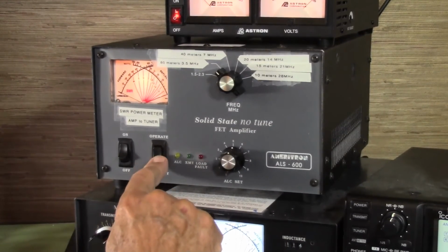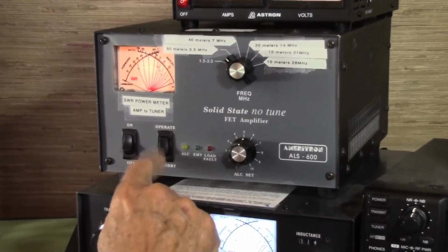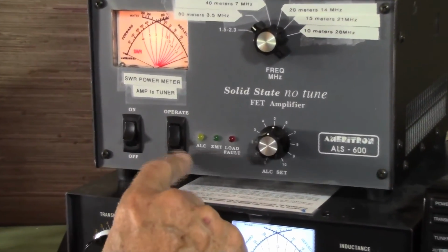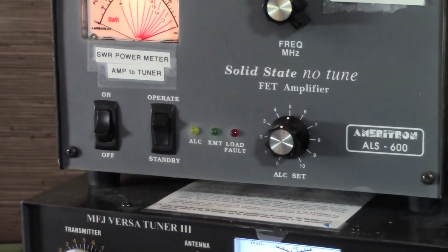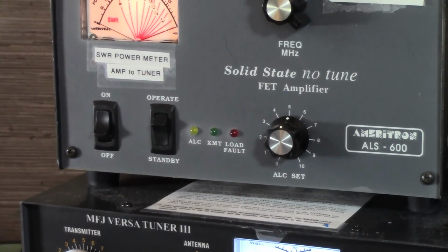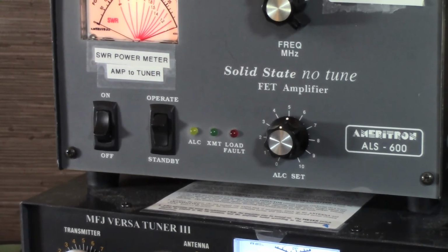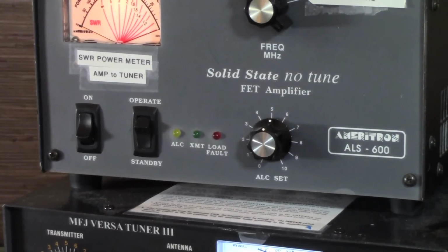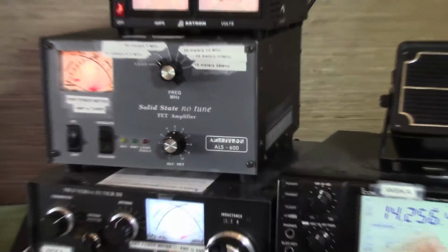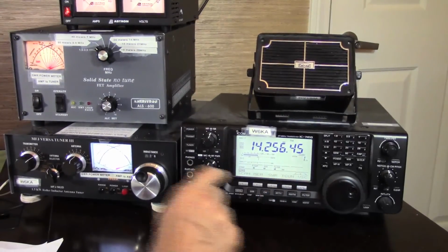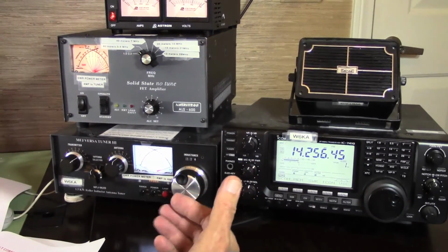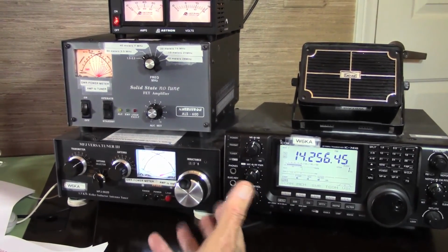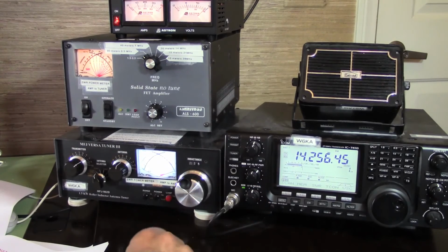I did show you that by switching this you can go back, but don't switch back right away. Let it sit and then check a few things. Here are the things you need to check. Be sure that your SWR is okay by, with this off, trying to retune it and make sure that the SWR is right, and follow the same method of tuning that we discussed earlier.